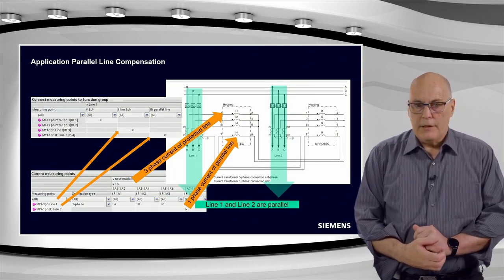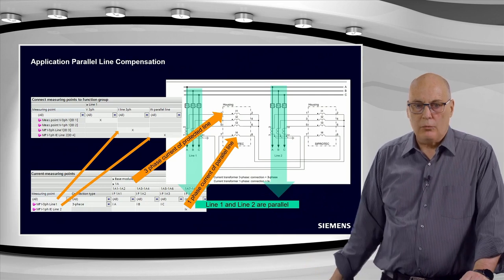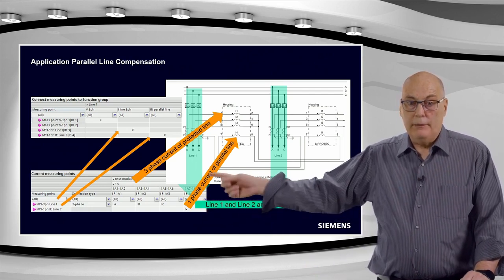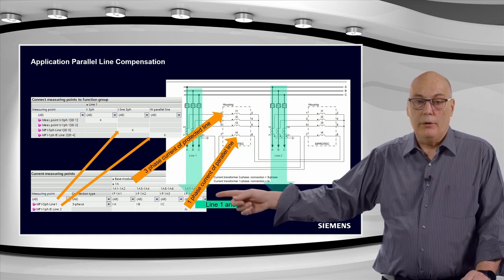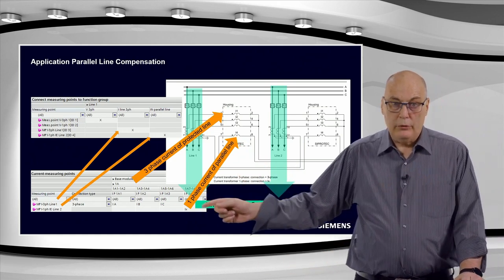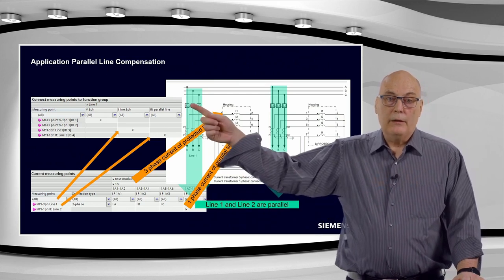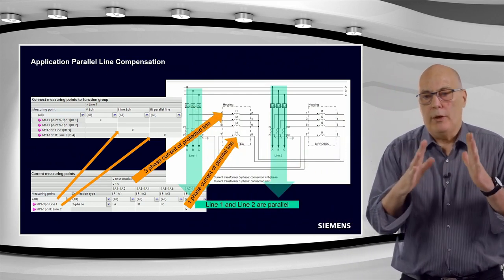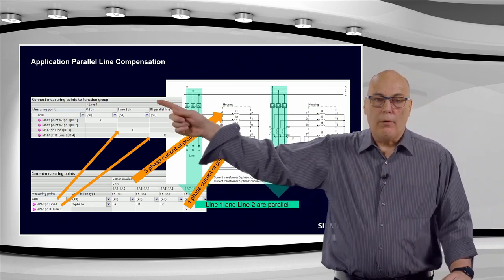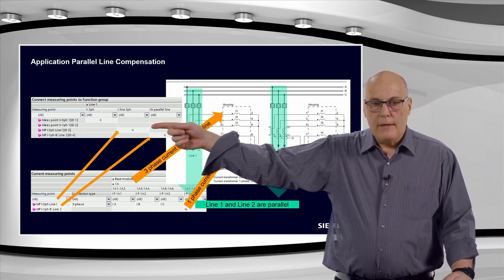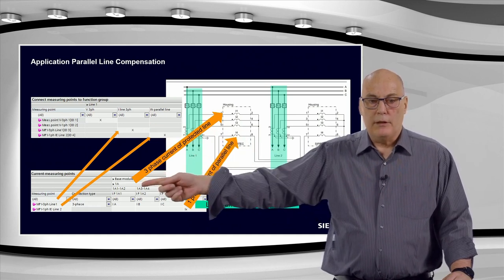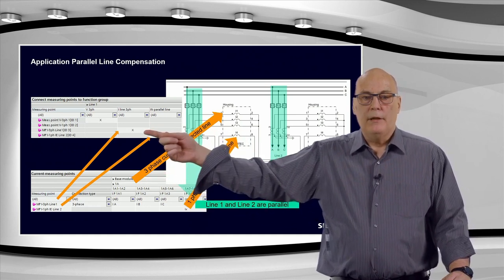Okay, that is the connection we did, and this is now just showing you how it was implemented in DIGSI. Remember, my parallel line current was the I4 current here. I assigned that to that point over here. That was our measuring point routing we did early on, and now interesting here in the function group connection. Remember, we had the blue blocks, which were the function groups. You were connecting your function group line to the CT. Here, this is this CT over here, the top CT, the three-phase CT connected here.